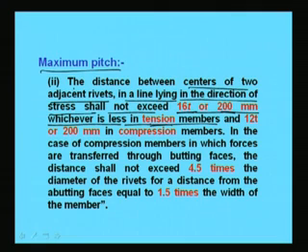So, in case of tension member, it should be 16 T or 200 millimeter, whichever is less, and in case of compression member, it will be 12 T or 200 mm, whichever is less. So, this aspect has to be also remembered, that the maximum distance P will be either 16 T or 200 mm for tension and 12 T or 200 mm for compression members.